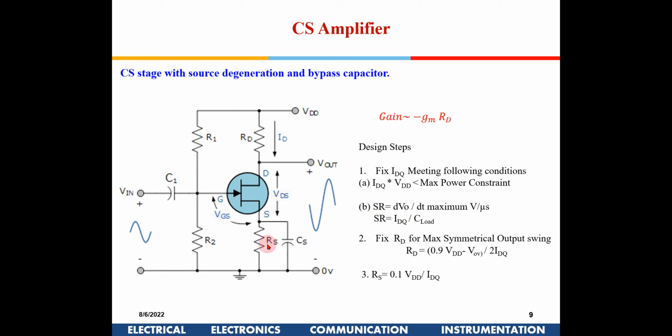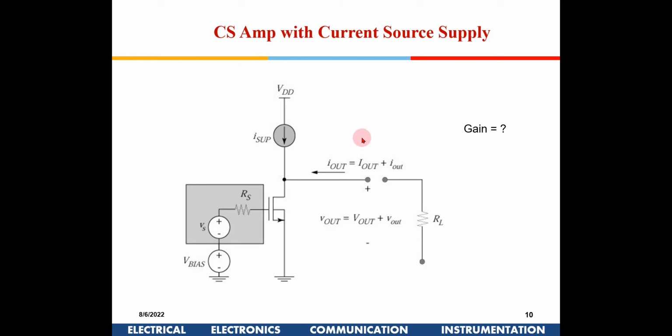Then we talked about how, since the gain was less, we put a capacitor out here. So in the AC signal, we got back the gain. Okay, full. So that is what we did, right? So the DC operating point remains stable, whereas the AC gain comes back by putting this capacitor. This we saw, right? And then we saw with a constant current source.